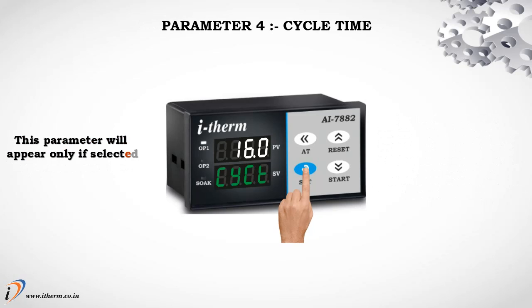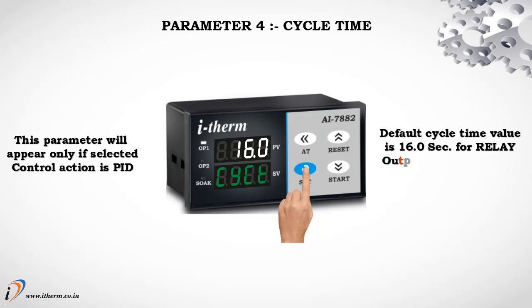Parameter 4, Cycle Time. This parameter will appear only if the selected control action is PID. The default cycle time value is 16.0 seconds for relay output and 1.0 second for SSR output.